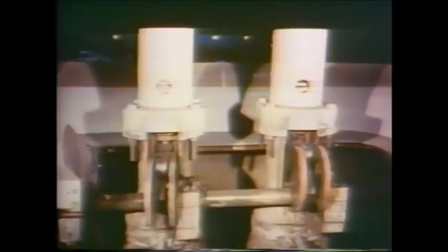This most often occurs between the high pressure and the intermediate pressure sections. Reheated steam is returned to the turbine through another set of valves, the reheat stop valves and the intercept valves. Additional protection of the turbine is provided by these valves. As you know, turbine speed is regulated by the control valves. If turbine speed increases, the turbine control valves compensate by closing.